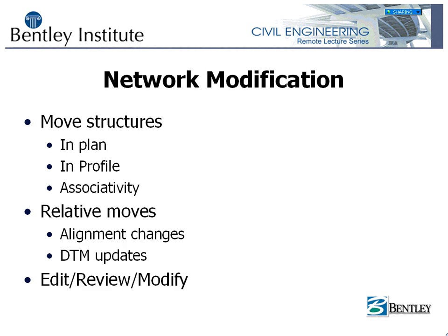Also for network modifications, I showed you moving the structures in the plan view. Let's go create a profile and do some moves in profiles. I've shown you the associativity with the product, and then I'm going to show you how I correct where I used the wrong DTM on this as well.